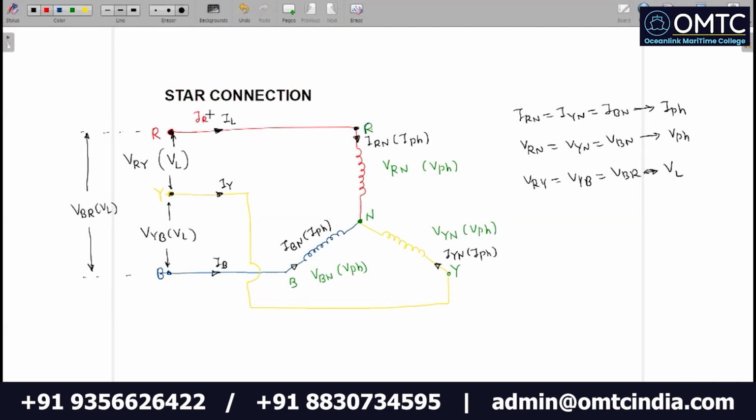This is IR, this is line current. Okay, this is also a line current. So IR, IY and IB, these three are line currents. Okay, so by observation we can say that the same line current is entering into the phase. So by observation I can say line current is equal to phase current.